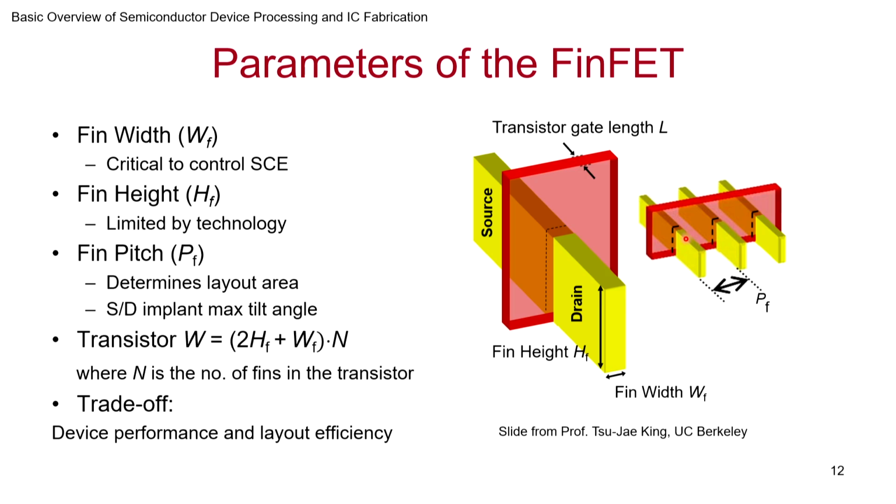For example, if I want to dope this source and drain, after the fin is built, you have to dope it by implanting from the sides. Now, if there are many fins standing next to each other, then there will be shadowing effect. This is similar to multi-storied buildings kept next to each other. In fact, certain cities have rules how close these buildings can be, because they want to make sure that people below get sunlight, and also of course safety and various other factors.